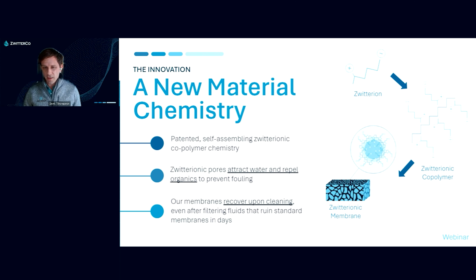But zwitterions are hydrophilic to the point of being hygroscopic. So they're very difficult to handle. They actually wick moisture out of the air. And so if you try to incorporate them into a membrane, usually it would result in a sticky membrane or something difficult to handle. So the real revolutionary change here was incorporating it into a hydrophobic copolymer backbone, which provides structure and allows these zwitterionic copolymers to self-assemble into a pore structure.